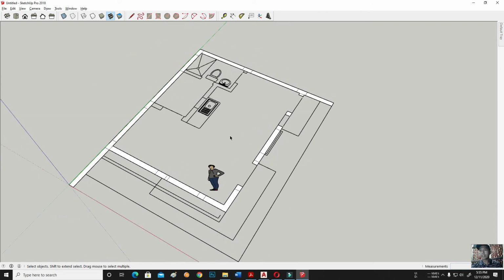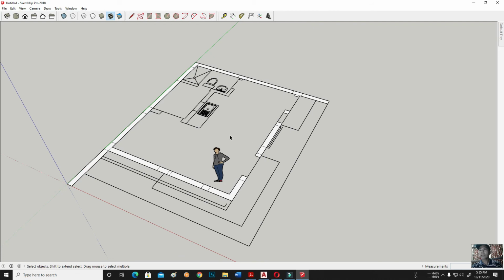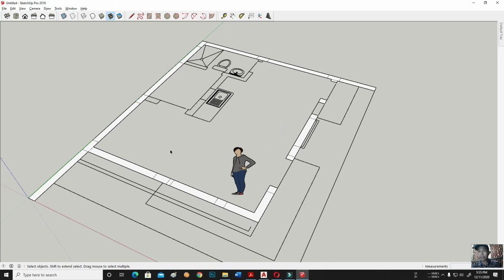Okay. So now, that's the time na pwede na tayong mag-extrude. Itatayo na natin. Extrude means itatayo na natin yung wall natin. Okay? Using the push and pull tool, by simply pressing the P key. Ayan. So, yan ang extrusion na tinatawag. Mapapansin mo dito sa right bottom, the distance, kung gaano kataas mo drinag pataas, yun ang makikita mo.